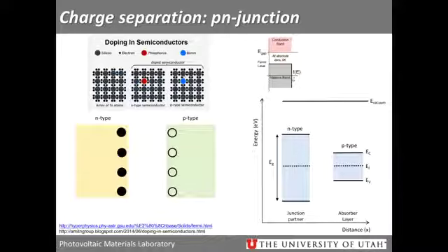such that they can be put across the load. So when we take intrinsic semiconductors, the Fermi level is kind of a measure. It is the point in a semiconductor or the band diagram at which the occupation probability is 50%. So for an intrinsic semiconductor, the Fermi level is in the middle of the band gap. Have you guys talked about Fermi levels?